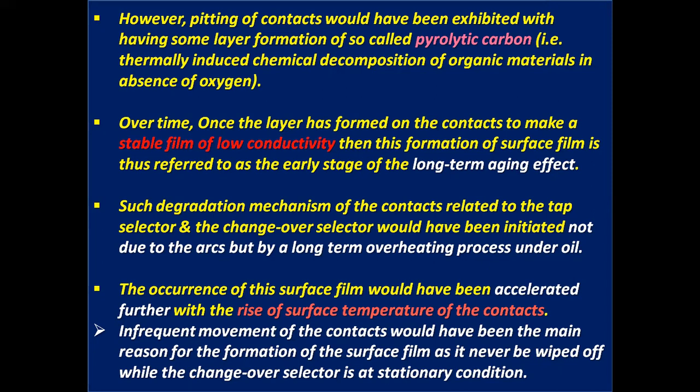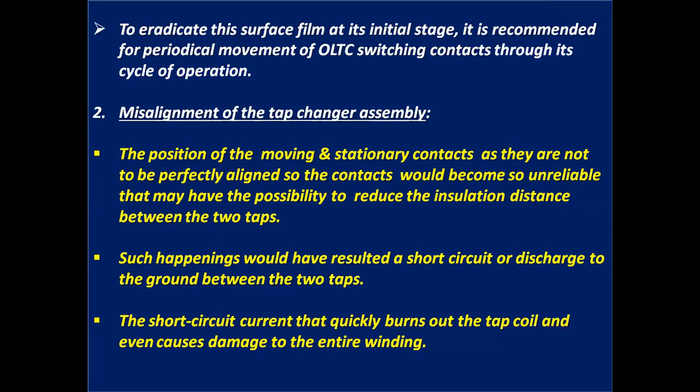Infrequent movement of the contacts would have been the main reason for the formation of the surface film, as it can never be wiped off while the changeover selector is in stationary condition. To eradicate this surface film at its initial stage, periodical movement of OLTC switching contacts through its cycle of operation is recommended.